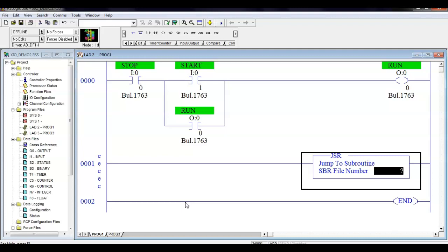Well, instead of me trying to go in and find that point, when they wrote the program, they wrote it as what? Subroutines. So I could go into the subroutine that picked up the block off the line and do what? I could reteach that point, I could reteach each point individually and keep playing around with it. So structured programs means we take a big program and we split it up into individual modules we call subroutines. And then to get to that, we use a what? JSR instruction.